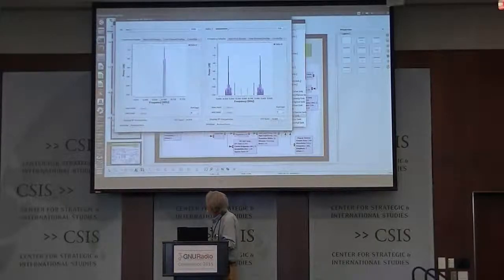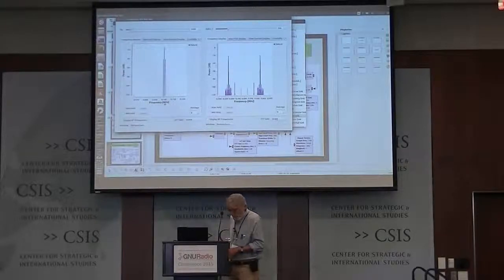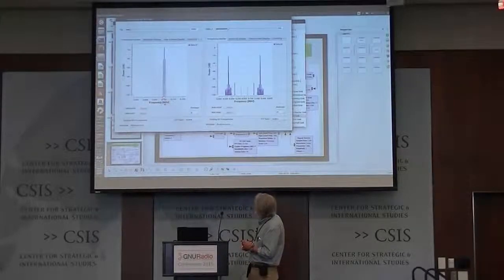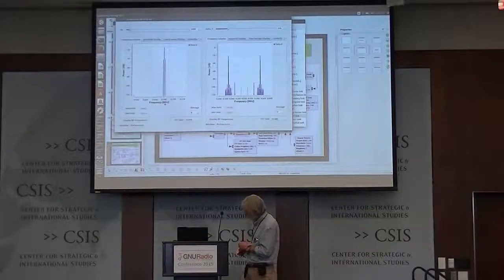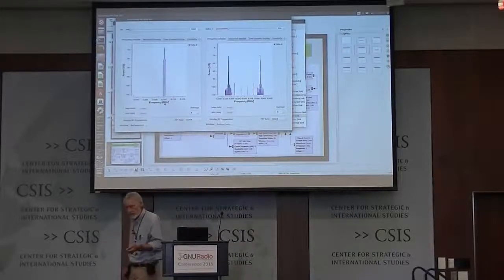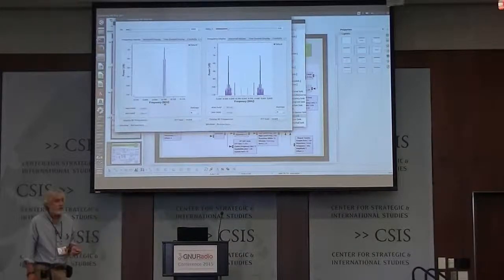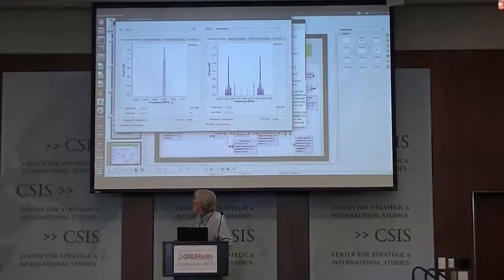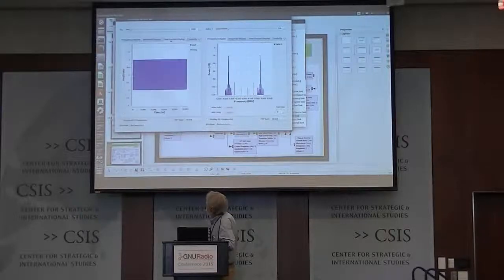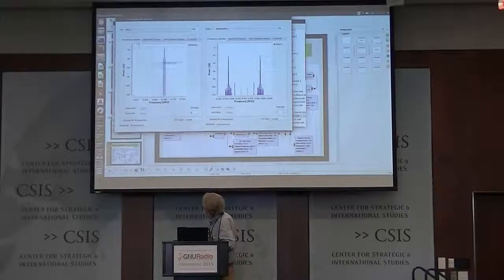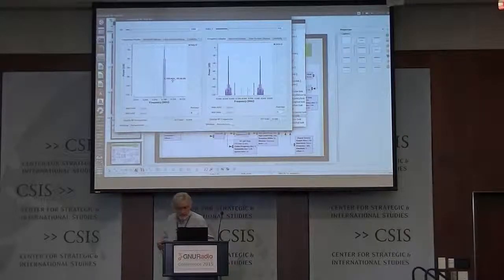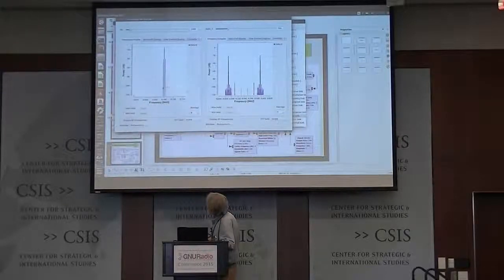Here we go. So we have here 100 kilohertz for the carrier, and then we have a 1 kilohertz message frequency. So you can see those two sidebands to the left and to the right of the main carrier, those are the plus minus 1 kilohertz. And this is actually a narrowband FM signal. If you look at it in the time domain, you can see it's a perfectly good FM signal with a constant amplitude. Of course, you don't see the FM itself in the time domain because it's way too little.